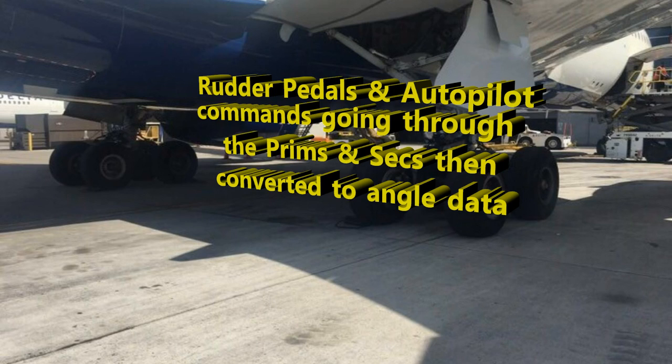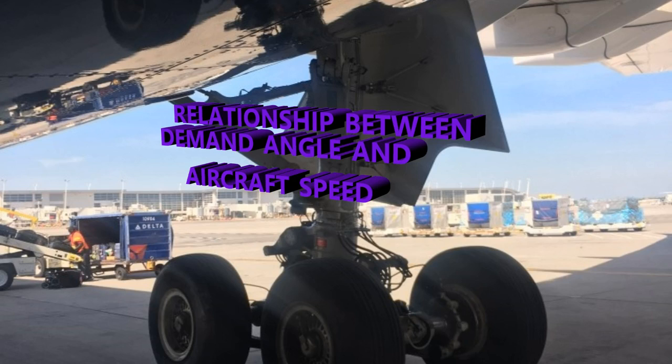So we have the demand orders coming from the rudder pedals and autopilot, which combined are converted into a demand angle. Then you have the hand wheel demand orders, which have a decreased angle deflection authority in relation to aircraft speed. There's a relationship between the commanded angles and aircraft speeds. The idea is to make sure there's not too much angle going on, left or right.